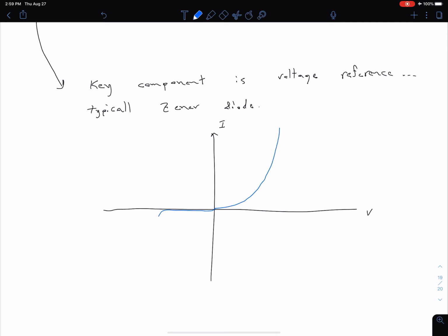And then once we reach breakdown for our Zener diode, the unique thing is that this voltage stays relatively constant. The idea is that as we move up or down on this line, maybe we start here, and for whatever reason our current is being increased through this diode, so maybe it comes over to 0.2, and then maybe the current decreases and it comes back to 0.3. What we see for all of these points is that they roughly correspond to the same breakdown voltage for our Zener diode, which we can label as negative VZ.